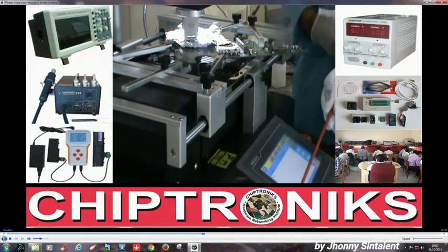Basically there are three stages. This stage is called the preheat stage, this is the reflow stage, and the soak phase, and the last is the cooling phase. So there are basically four phases in the BGA rework cycle. One, preheat, where the entire board is preheated. Then reflow, that is, the temperature is ramped up, and the soak phase, when the ball gets melted.